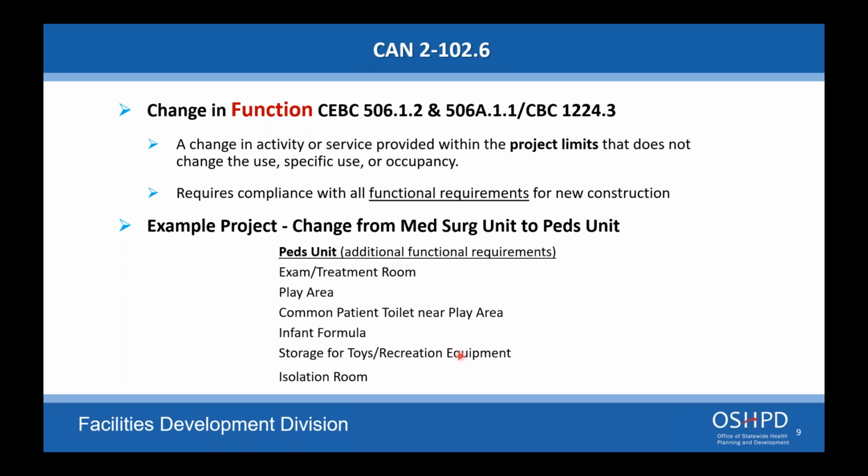We're not going to make you go back and re-conduit or re-brace the entire facility because you have a head end on the other side of the hospital. Again, all new elements do need to be anchored and braced according to new code, but you can reuse existing conduit. Hopefully that answers the question.